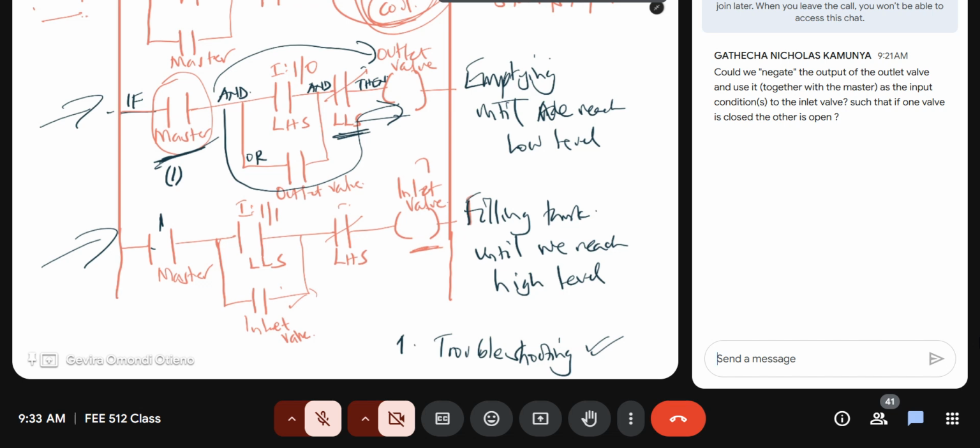But now in reality, you're having a few issues. So always try and avoid over complicating or over borrowing from previous ranks, because then it might give you issues. Unless you're so good that even in troubleshooting, you can remember each of those systems the way they were, and you can quickly troubleshoot each line, remembering exactly the states of the previous conditions. But that becomes a very difficult thing, especially if your ladder diagram is 100 rungs. Human beings don't really have the capacity to remember conditions of 100 rungs. If you're dealing with 2 rungs like this, that one you can do, you can remember.